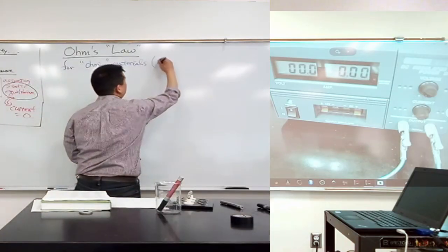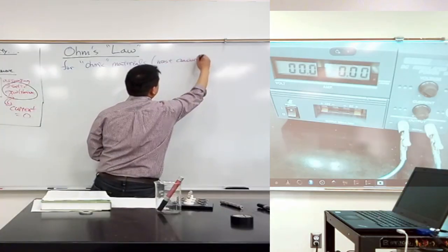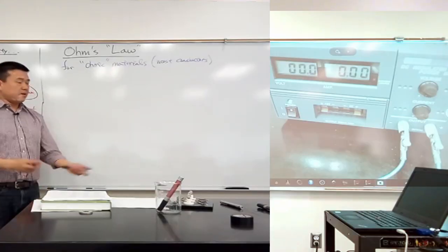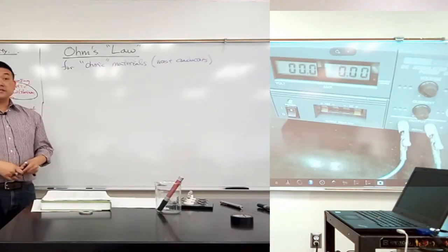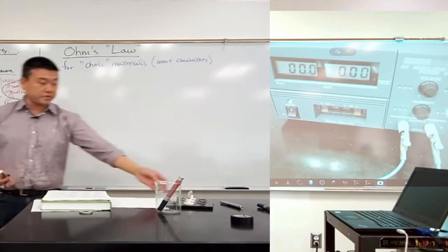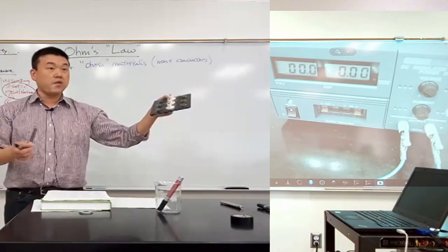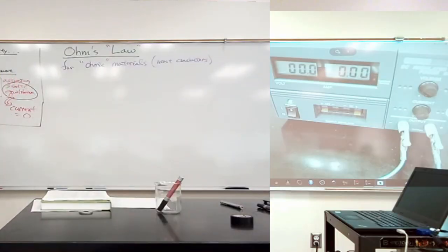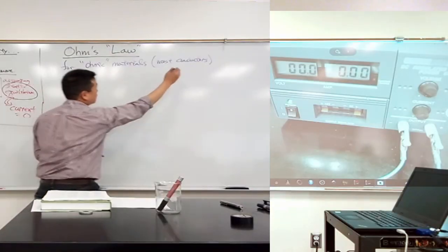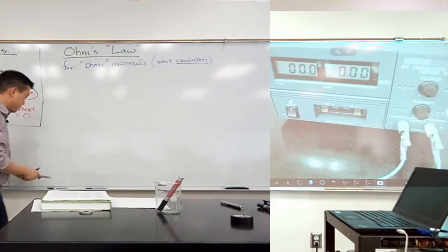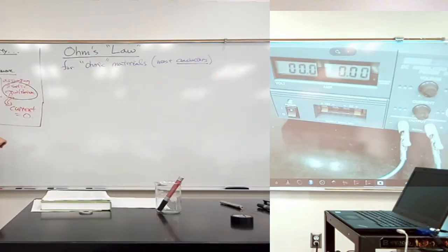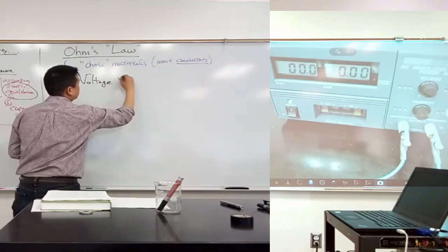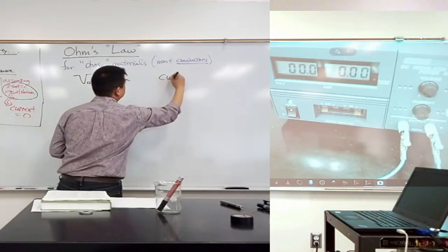It's sort of self-explanatory, right? Ohmic materials include a lot of different things. It includes most conductors. And in fact, it might include all the conductors, because the things that don't obey this are like semiconductors. And sometimes when the conductor's temperature changes a lot, it can be considered non-ohmic, in the sense that the relationship isn't strictly linear. But for materials that obey Ohm's law, essentially most conductors, this relationship holds. The voltage you apply is proportional to the current that you get.